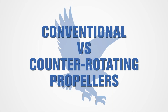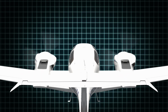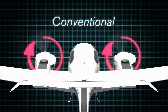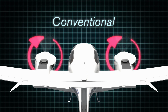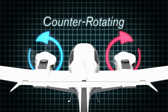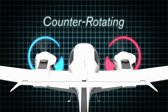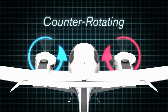Conventional versus counter-rotating propeller installations. Earlier, we had discussed conventional and counter-rotating propeller installations. Conventional propeller installations have both engine propellers rotating clockwise from the pilot's seat looking forward. This is the same direction the propeller rotates in the Cessna 172. Counter-rotating propellers, on the other hand, have the propeller spinning in the opposite direction. One propeller rotates clockwise and the other counterclockwise. This design minimizes the effect of torque and other turning tendencies.